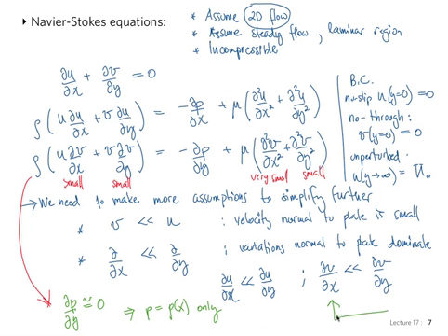The boundary layer is very thin, and all the viscosity effects are in this boundary layer. Outside the boundary layer, somewhere in a large enough y, the fluid can be considered completely inviscid. If it's completely inviscid, I can use Bernoulli's equation to find the pressure, and therefore pressure essentially is known from the conditions at the unperturbed locations.